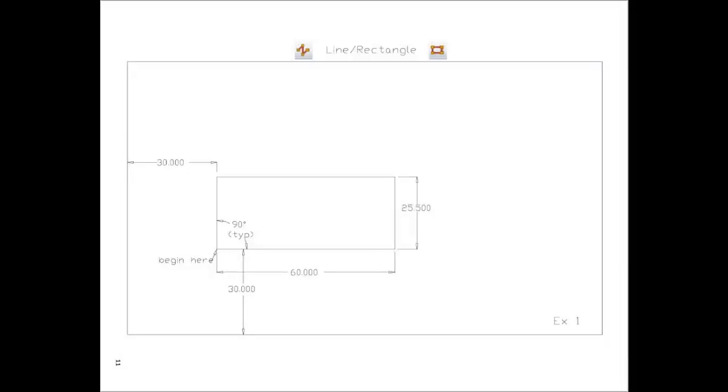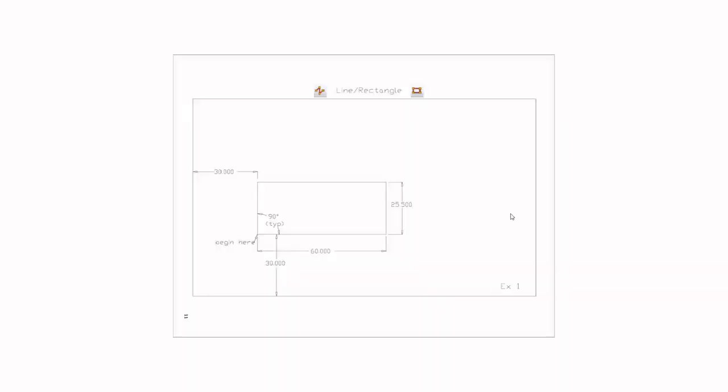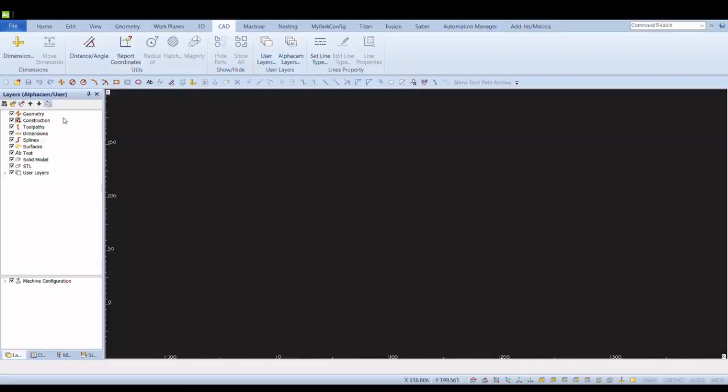Example 1. For this example, we will go over how to draw a line and a rectangle. First, we'll draw the large rectangle on the outside, which is 13 feet wide by 8 foot tall. Then we'll draw the box on the inside with the rectangle command, and then show another way with the line command. For this tutorial, we'll be using the Park Industries Quick Access Toolbar whenever possible. This Quick Access Toolbar has most of your commonly used commands you're going to use day to day.